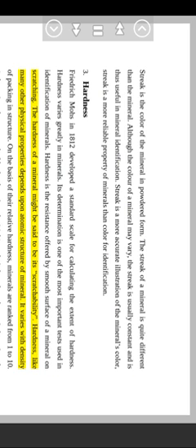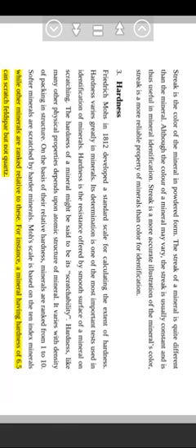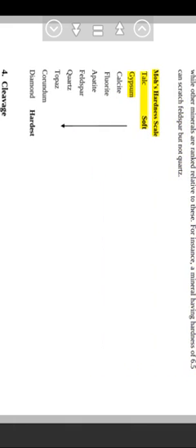Hardness, like many other physical properties, depends upon the atomic structure of the mineral. It varies with density of packing in the structure. On the basis of their relative hardness, minerals are ranked from 1 to 10. Softer minerals are scratched by harder minerals. The Mohs scale is based on the 10 index minerals while other minerals are ranked relative to these. For instance, a mineral having a hardness of 6.5 can scratch feldspar but not quartz. Mohs hardness scale: talc softest, gypsum, calcite, fluorite, apatite, feldspar, quartz, topaz, corundum, diamond hardest.